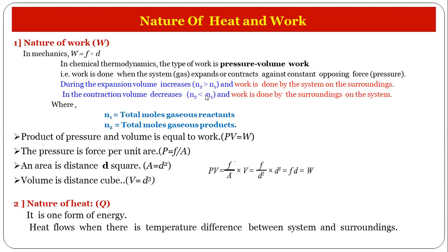And opposite to this, when contraction takes place, the volume decreases, and work is done by the surroundings on the system. See here, work is done by the surroundings on the system. So these two conditions are very important. During expansion, work is done by the system on the surroundings, and during contraction, work is done by the surroundings on the system. It is opposite. Actually, this thermodynamic work and mechanical work are the same. This is explained here in detail.